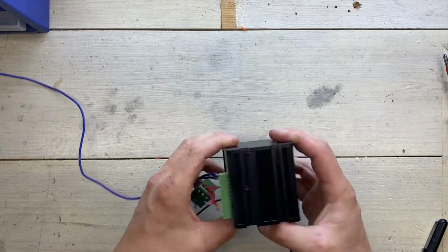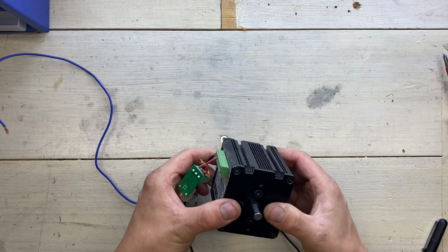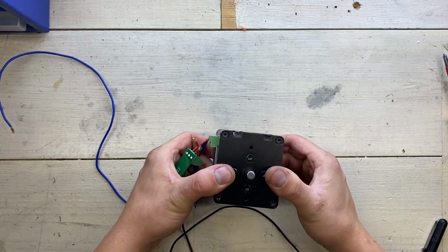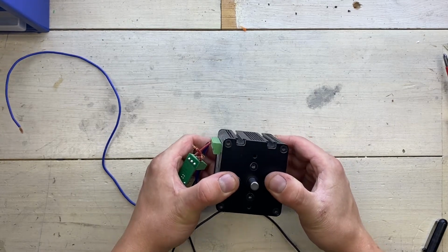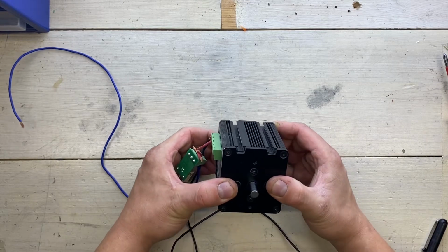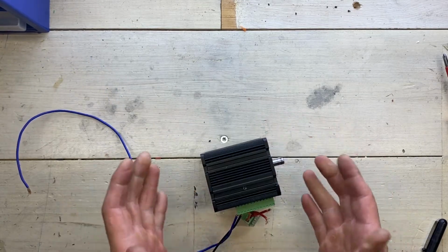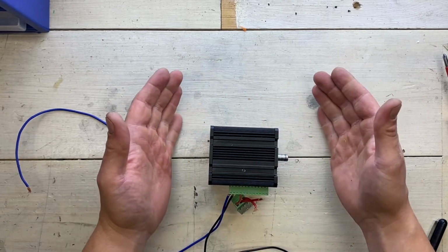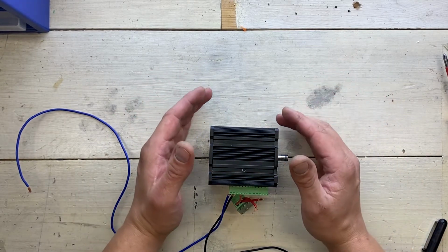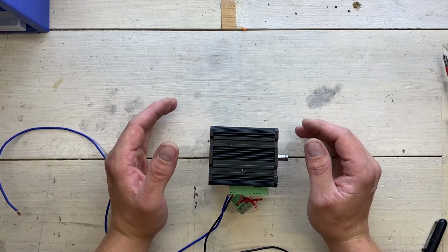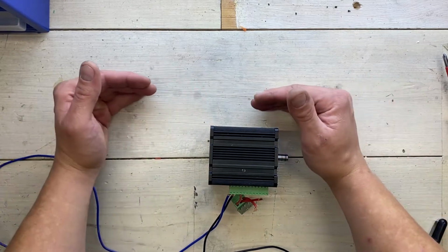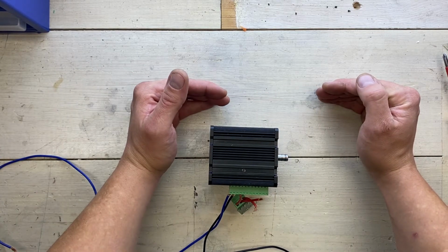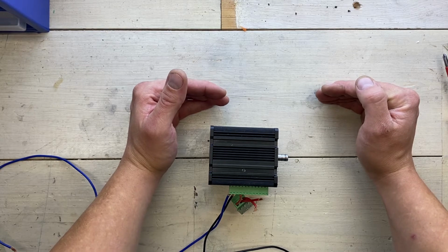Servos are used on almost all professional CNC machines. And for a good reason. They are extremely powerful, extremely fast, and extremely accurate. And since you have the entire feedback loop inside the driver that can be either internal or external, as long as you have a solid mechanical system, you have no reason to actually measure the position of the axes, as was done on old school CNC machines.